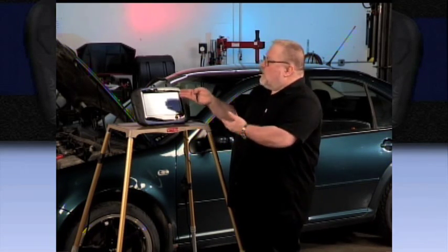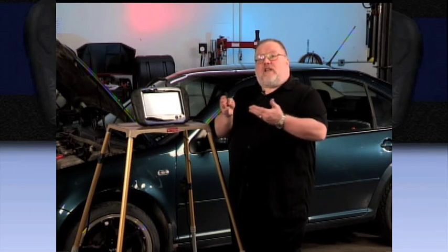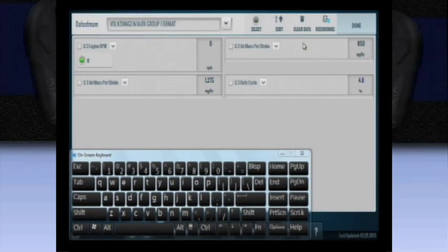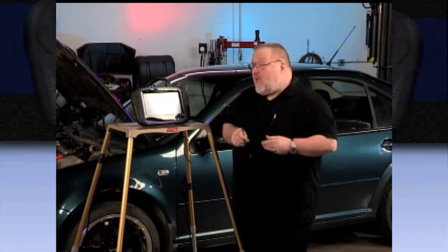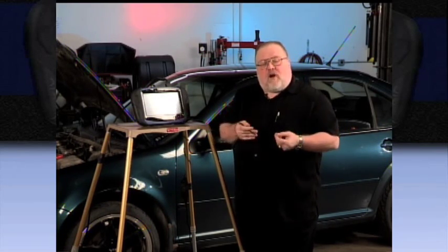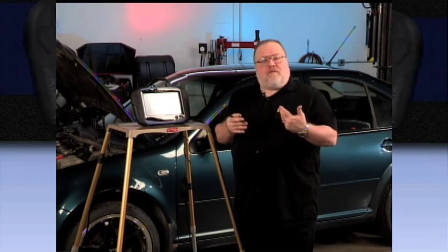Now, if I had a situation where that mass airflow reading was significantly lower than those numbers that I was talking about, now I'd want to start doing some physical inspections to determine, do I have carbon buildup, do I have a physical problem actually within the intake manifold itself? All right? Another potential problem for low power would be a problem with the vehicle turbo.